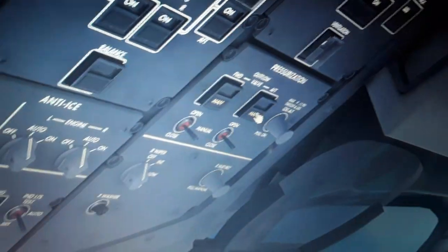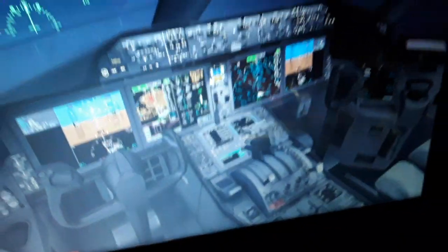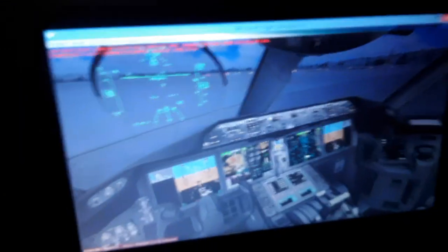So all these things from the engine's functions are controlled by the FADEC. The engine's display, when you move the thrust levers, you give command of the FADEC. So we have the GEnx engines on the Boeing 787-900 aircraft. Also have a gearbox installed with the FADEC. The FADEC are the dual channel redundancy. One channel fails, the other takes over. The full authority digital electronic control computers control motors and display all the engine function and data you see in the upper and lower display.